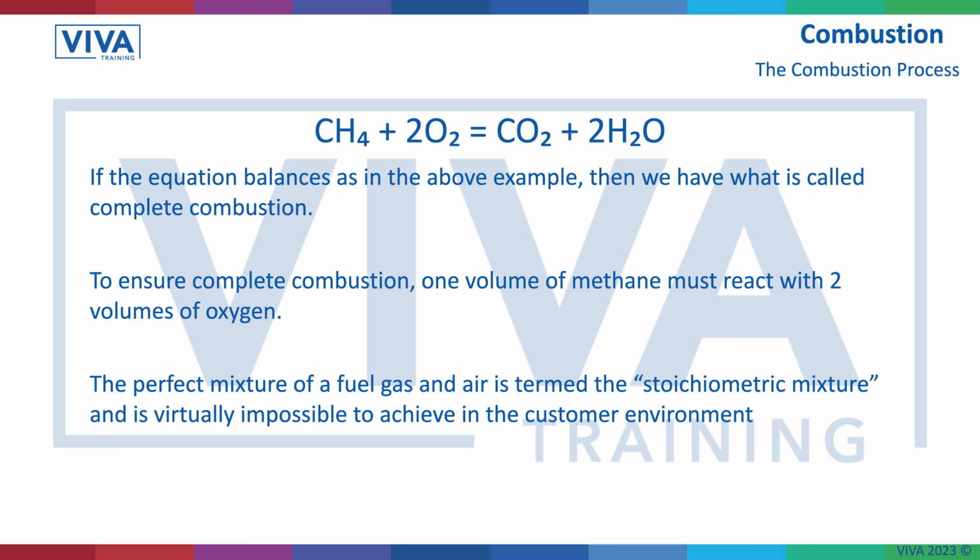In the real world though, it's virtually impossible to achieve. The reason being is we always put more air in than necessary for combustion, because we don't want it tipping over to where it's fuel rich and oxygen lean. And we'll come on to that as we start looking at incomplete combustion.